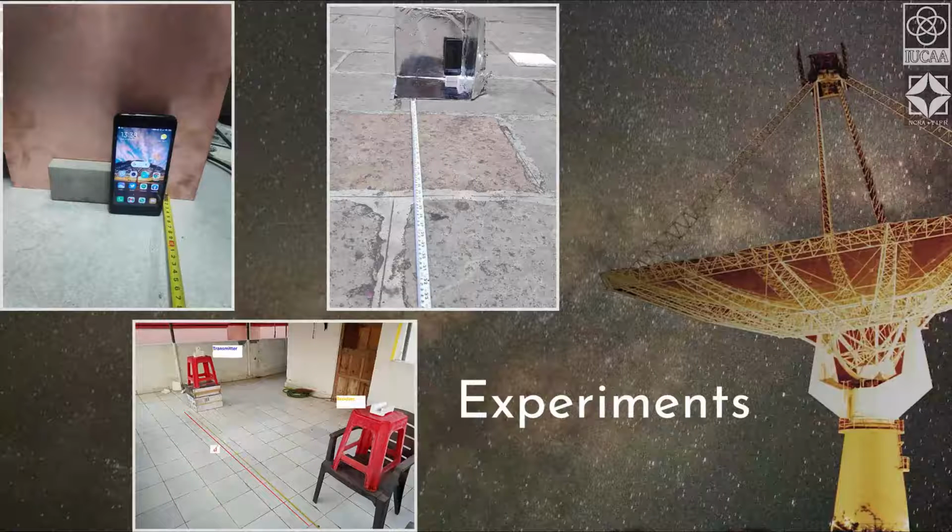You can divide it by 4 and keep your transmitter at lambda by 4 distance, which comes to almost 3.3 to 3.5 centimeter. You can see there is a change in the power. The receiving power is slightly increased, so that you can verify here.